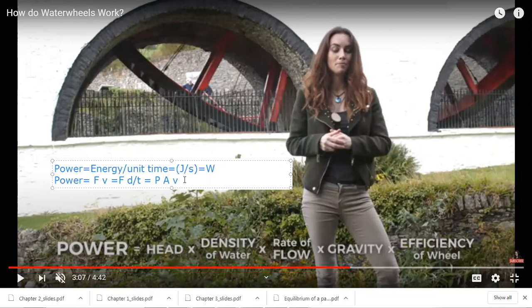I think you know it. It's the flow rate, okay? Because P, the unit of P is Pascal. It's pressure, so it's Newton per meter square, okay? Your area on which you are applying the pressure is in meter square, and the velocity is in meter per second. Now, if you multiply the cross-sectional area by V, this corresponds to the flow rate, okay?